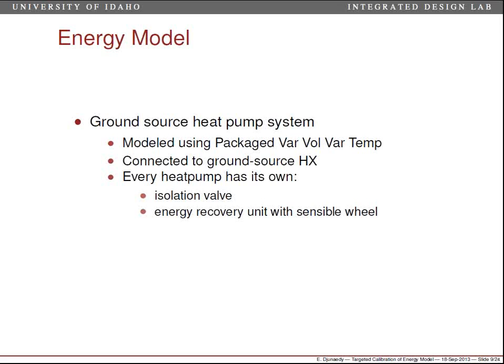So we will see later, it's only a handful, probably a bit more than half of the heat pumps, that have this isolation valve. And the second one that is very important is that every heat pump has its own energy recovery unit, which is not the case because the building has a dedicated outside air system with its own air loop, with its own single heat recovery unit up on the roof. And this will raise a number of questions. For example, how do we include the fan at the makeup air unit? Because if we model it this way, then the fan will be the fan of the heat pump. So there is that question, but we'll address it later.